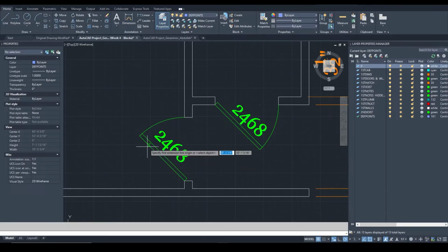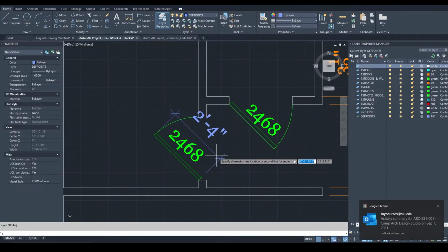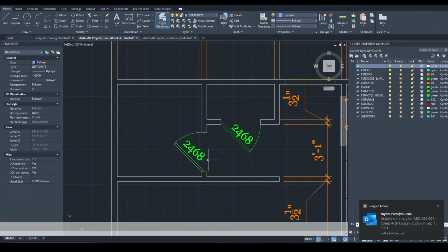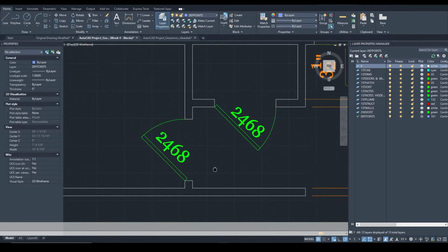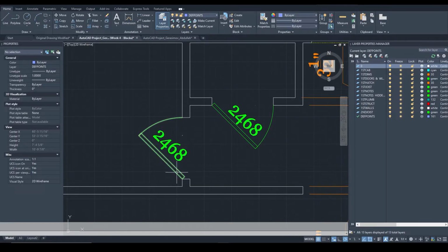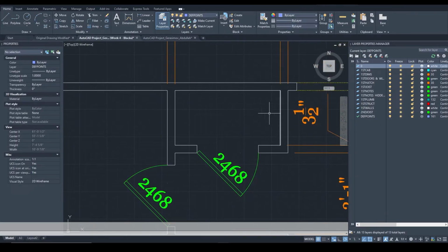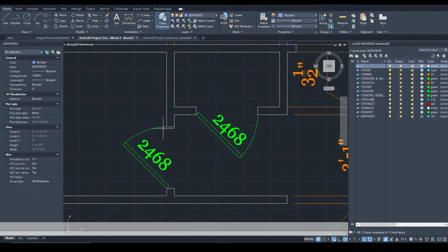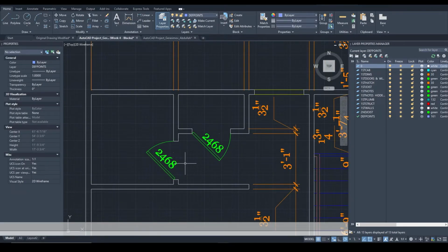And the way you can check this is a 2'4". There you go. It's a 2'4" door. The way you place these interior doors is you can either center them on the space or on the hallway, or you can offset them from the edge.